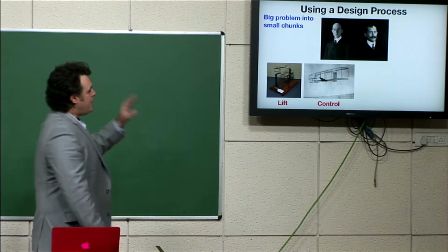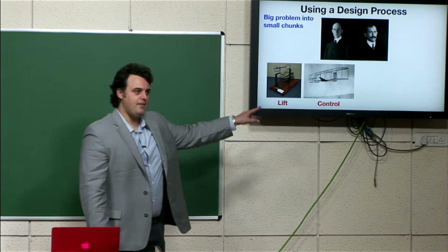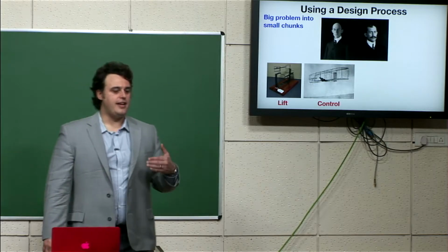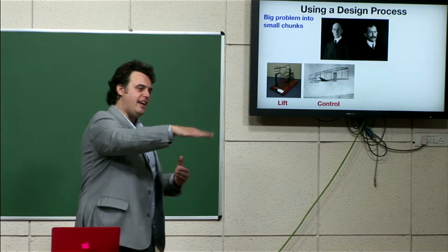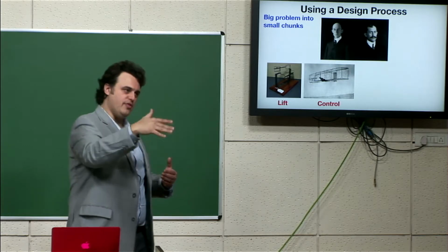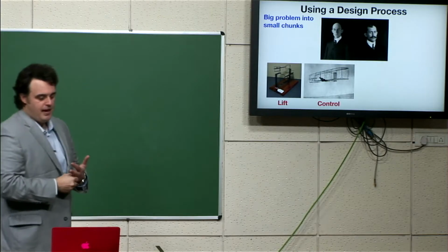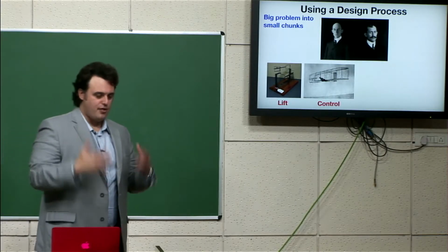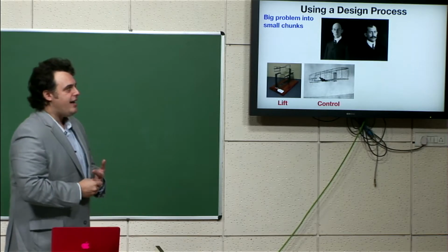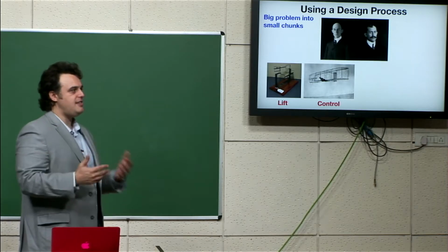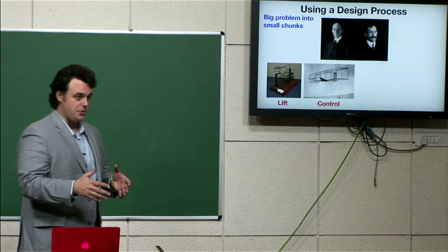Then, what they realized is they could characterize lift to drag, they could control the plane, and because they knew lift to drag, they could calculate how much thrust power they would need to move through the air to get enough lift, right? Thrust force times the velocity is thrust power. And so when they were designing the first flyer, they realized they needed 8 thrust horsepower. That's the drag force multiplied by the velocity. And they figured they could get a 66% efficient propeller, and so they needed 12 mechanical horsepower coming out of an engine.